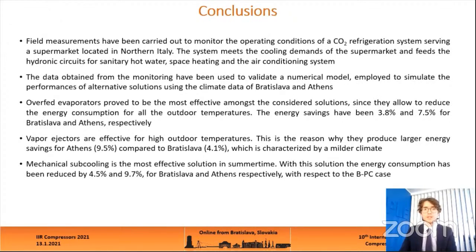In conclusion, field measurements have been carried out to monitor the operating conditions of a CO2 refrigeration system serving a supermarket located in northern Italy. The system meets the cooling demand of the supermarket and feeds 3 hydronic circuits for sanitary hot water, space heating, and the air conditioning system.